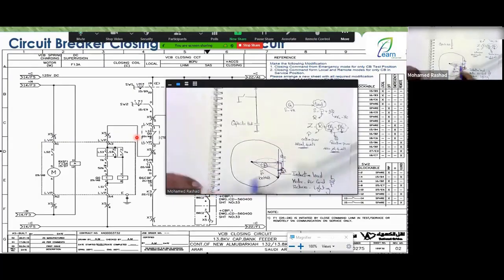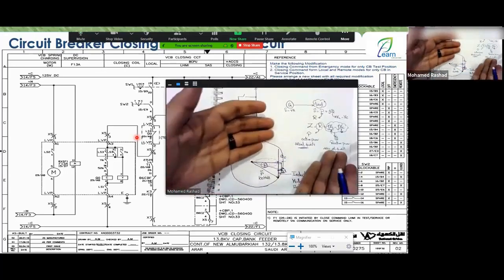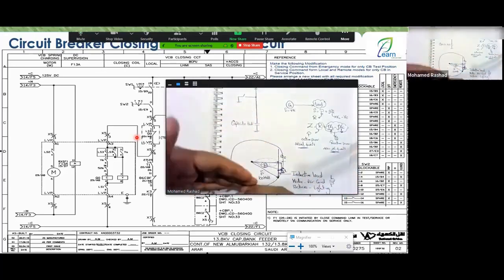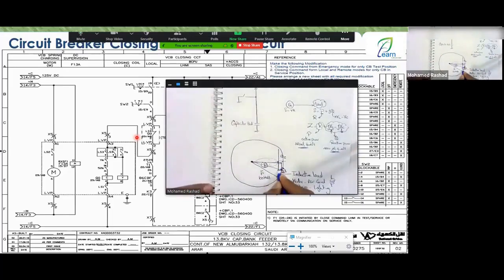The capacitor provides Q. So what will I do if I place a capacitor here that provides Q? Instead of having all of this as my Q, when I add a part QC, this part is subtracted from that part, leaving me with only this portion. And if I increase QC even more, I might reach a point where I don't have any QL at all, and all my S is converted to what?